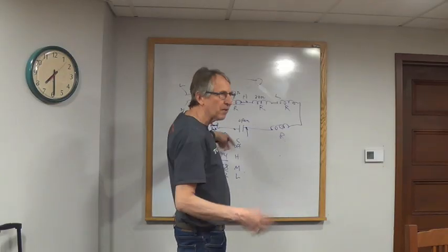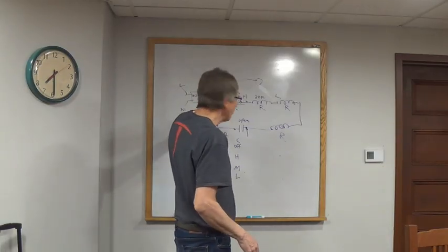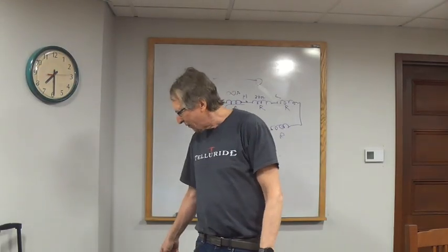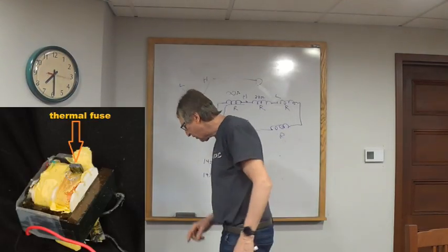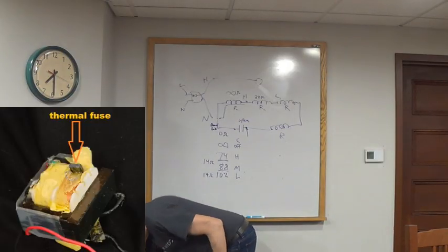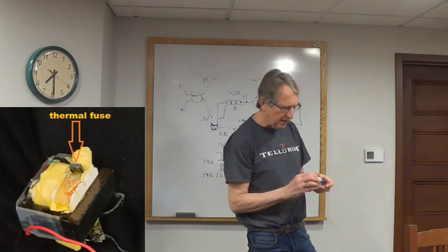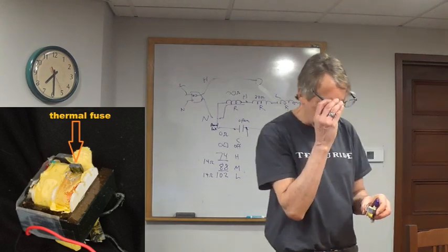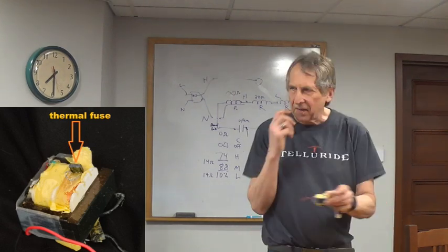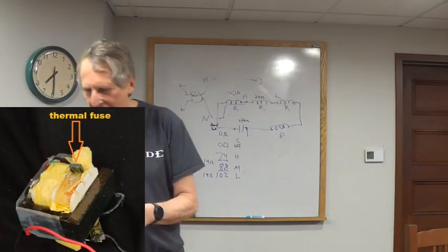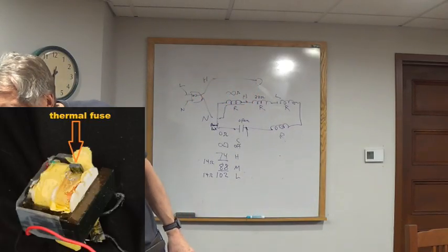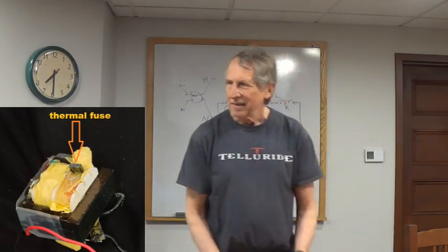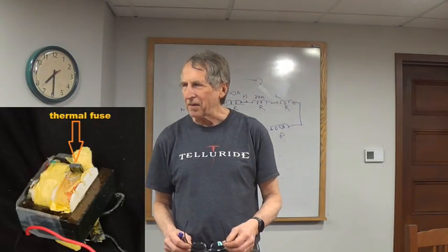All right, so if all of these, for example, are infinite, that probably means your thermal fuse is blown. I don't really want to take that fan apart again to look at the thermal fuse, but I do have this. It's not exactly from a motor, it's actually a transformer, but it's got the same concept. It's got a thermal fuse. I dug it out here and I broke some wires, so this coil is probably not recoverable. But that's what the thermal fuse will look like.